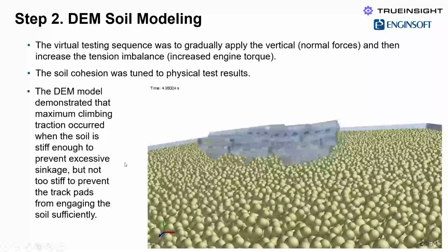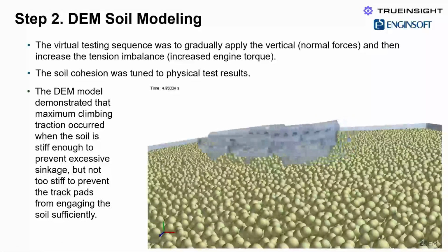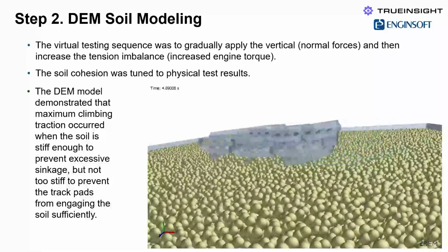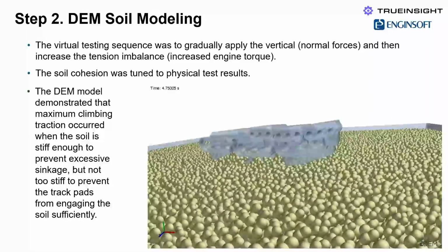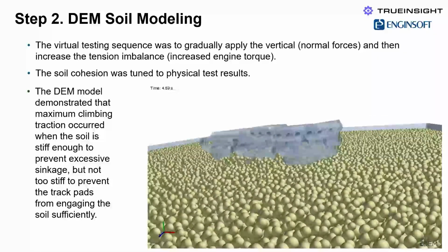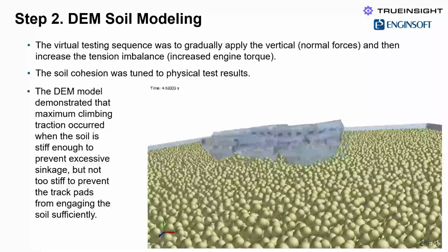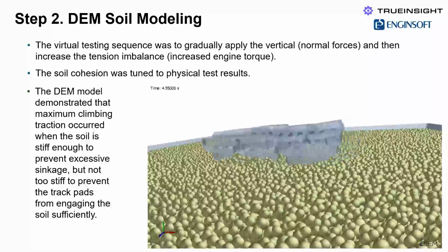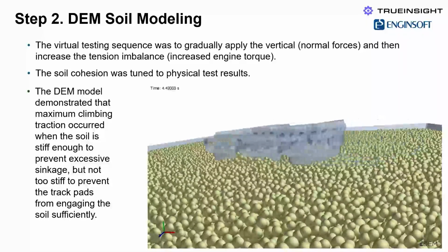So if one were to think about friction, what is the friction? This is what this towing operation is all about: to look at how much traction is available, and traction is related to friction. So in the case of basic friction between two rigid bodies, we're used to the notion that we have a coefficient of friction for the static case with no relative velocity, and then as we get relative velocity, that dynamic coefficient of friction is lower.